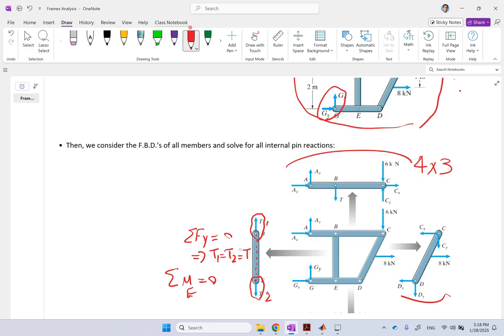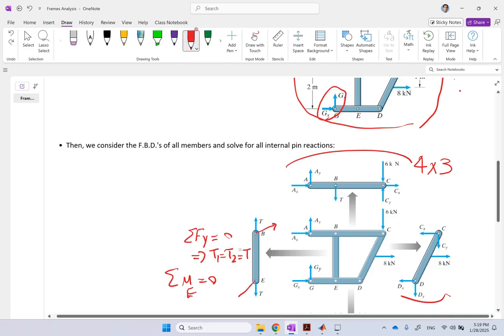Okay? If one of them has a little bit of offset, so one of these T's is not on this line, for instance, is on this line, not only does it create a horizontal force that this one doesn't have and cannot cancel, it also creates a moment. And you might say, well, how about this? So I say there is a T here in this direction, and there is a T on that. So basically the equal and opposite of that.